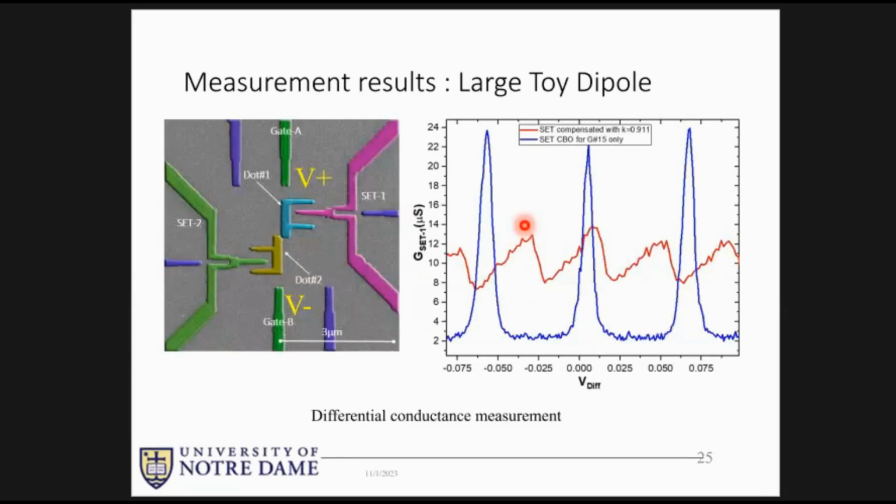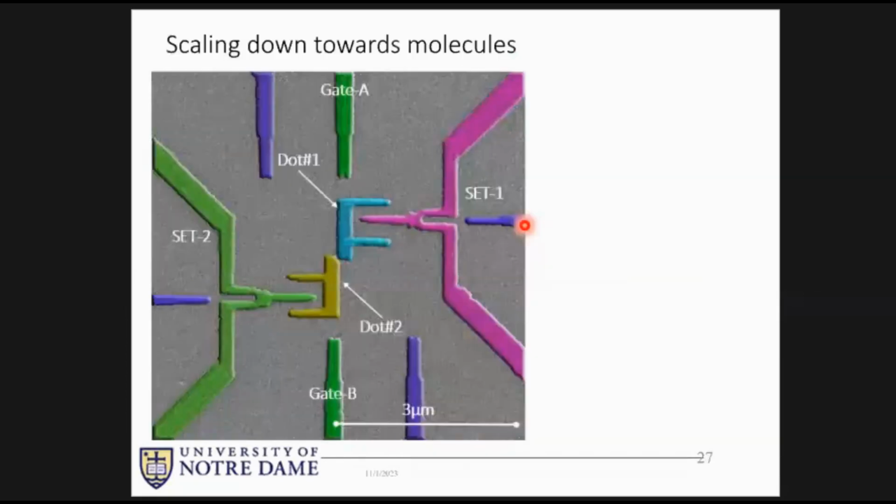It corresponds to a small change in delta Q perceived by this single-electron transistor. Let's say we sit around 0, we apply some bias, so we put 1 electron to go this direction, and we'll be getting more and more electrons to here, removing more electrons from the other one. And it gives you this characteristic sawtooth function, which you observe as the red curve.